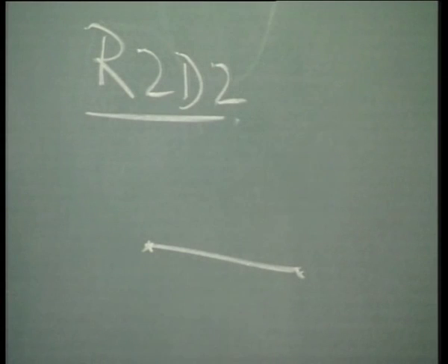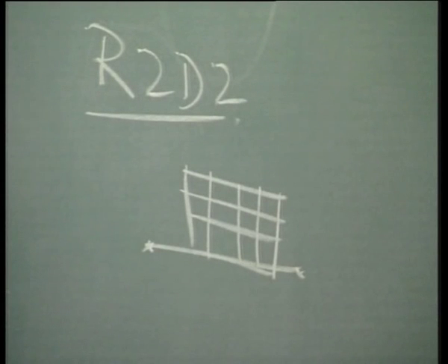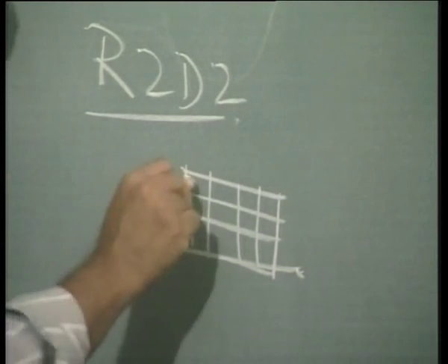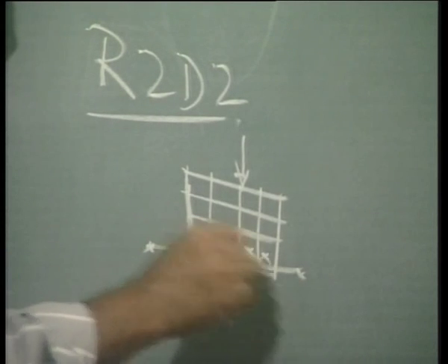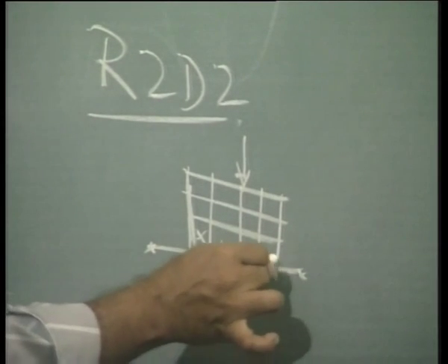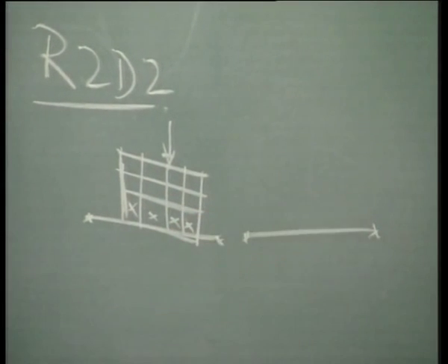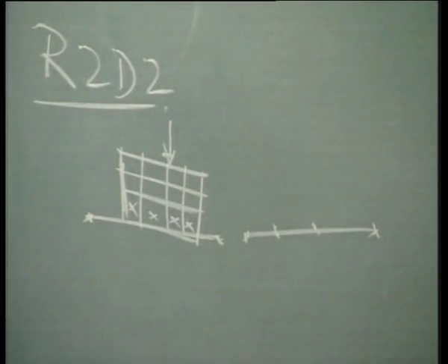and then you can have one more set. Say, for example, this is the material that we are going to compress. Then we can say that these elements are in an element set, and that the surface, the bottom of this element defined as a surface, is the one which is going to be the slave surface. Or in other words, automatically when I say this is the slave surface, automatically the nodes are extracted.